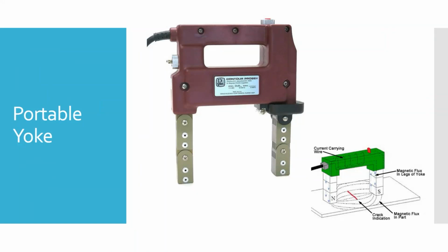And so if we found something magnetic, we would have to take one of these yokes. If it was a landing gear leg, we'd bend the two little ends so they wrap around or hug the gear. One way to get rid of magnetism is to create a magnetic field and then reduce that magnetic field. Turn it down. Or in the case of a landing gear leg, you put the yoke around the leg, press the button to activate the field, and draw the yoke away. The magnetic field at that gear leg gets lower and lower and lower, and it actually re-scrambles everything. So you do that a couple times, and then you check your landing gear leg to make sure it's not magnetic anymore.